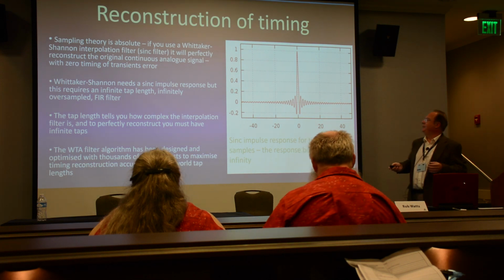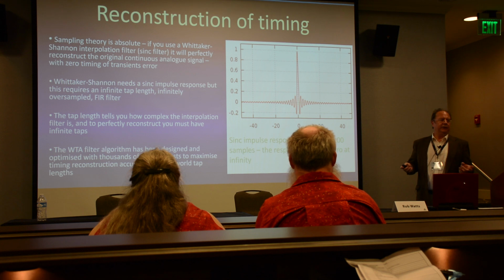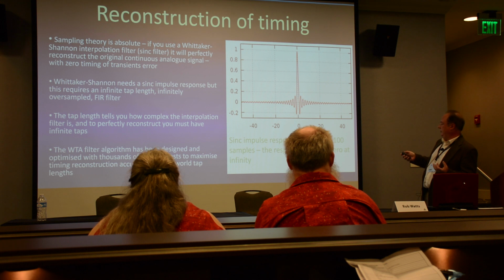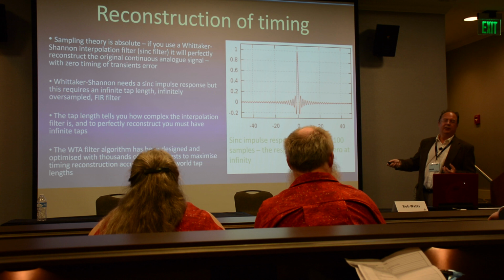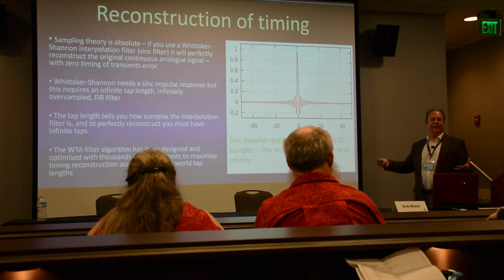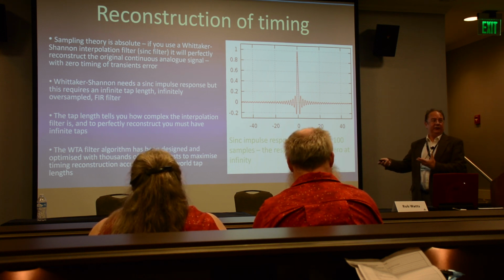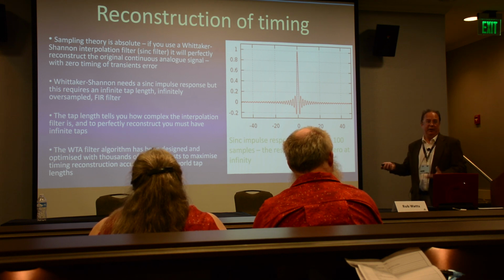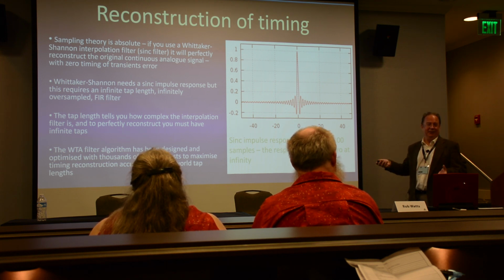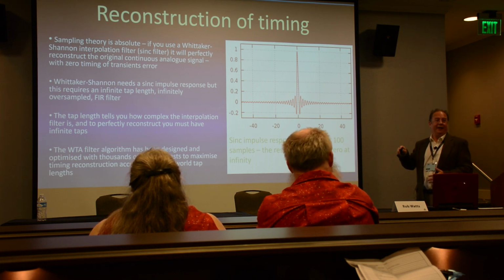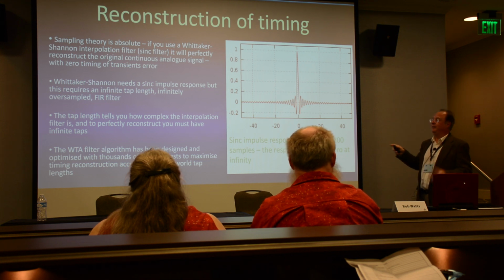So, how is the reconstruction done? You use something called a sinc function. This is just a simple illustration of the impulse response of a sinc function, and this thing decays away to 0 in an infinite period of time. So it requires an infinite delay. If you were to construct such a filter, you would need an infinite amount of processing to do it, which of course is impossible. But this is what theory is telling you, and the theory is a fact. It's not something that somebody's made up.